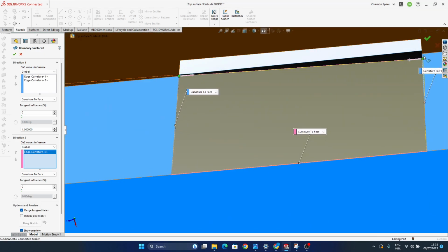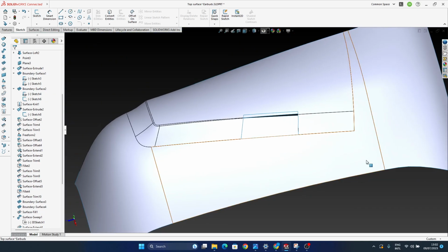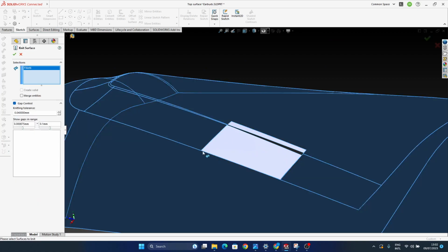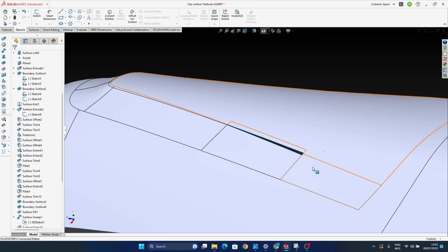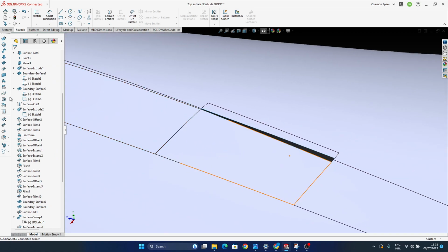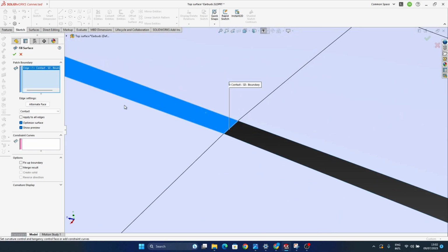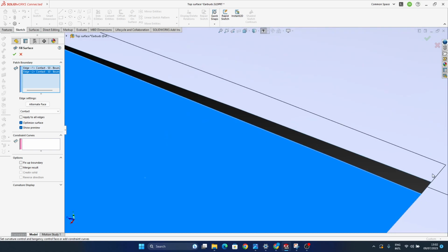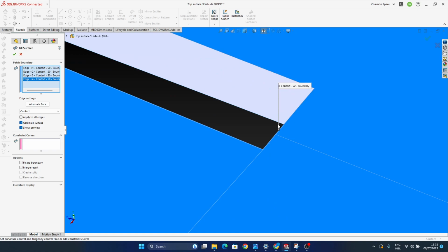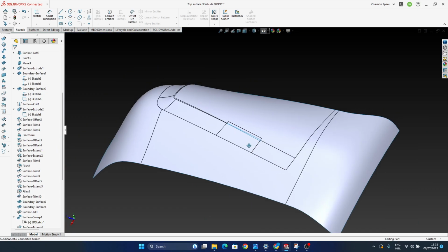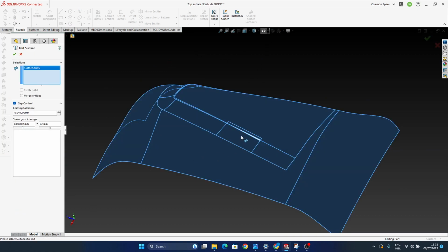It should match. I shouldn't have a problem. Okay, never mind. So we arrived in here with, right? So if I am, for example, merging the surfaces together now, and if I will just fill them up, I could also use the boundary surface to connect them at the very end. I will just fill them up, and I will say, okay, I want curvature on all, because it shouldn't have a problem to apply curvature on all. And now I would just knit the surfaces together.